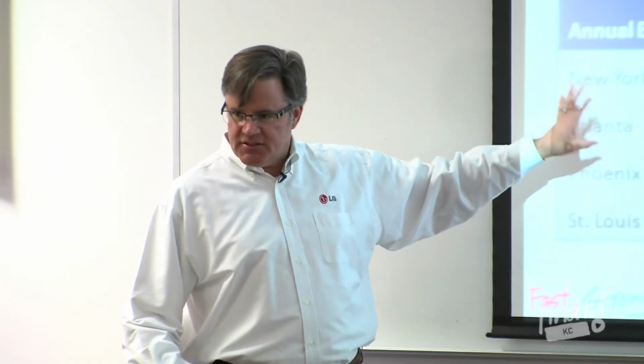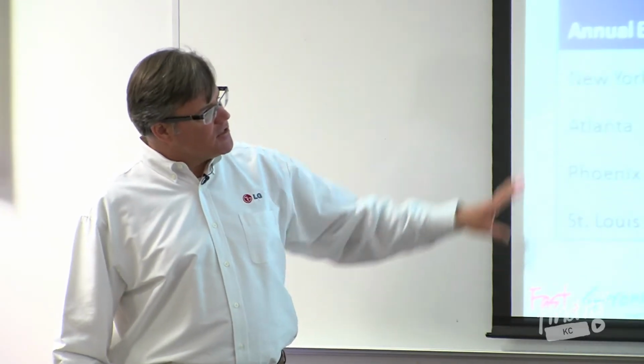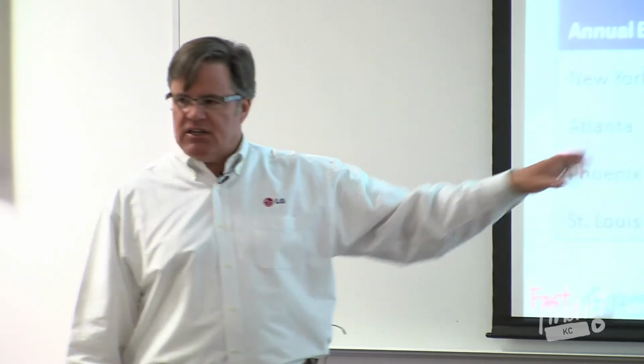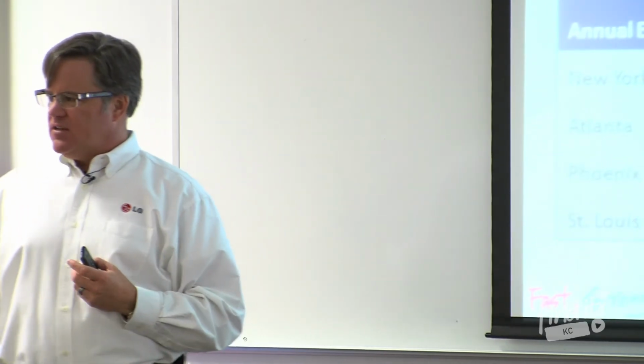So obviously everybody has different seasons, different times, and so this is the kind of cost savings that we see when we start to compare VAV system versus a VRF system in this example building across those different markets. So you can see when we're talking about VAV, it's nearly a quarter savings, 25% savings across a VRF system. So this doesn't include the difference in how these systems operate, how these systems maintain. This is just energy efficiency.